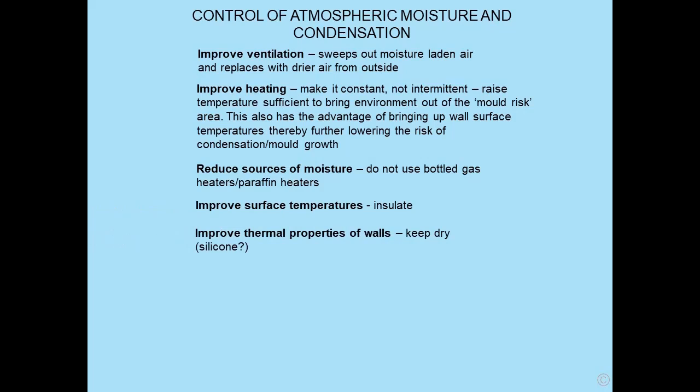Keep dry. For example, if you take a solid wall and it starts to get full of water from a long rainstorm, one of the factors that affects the thermal property is the capillarity, the air in the capillaries of the wall. If that is replaced by water, then it reduces the thermal property of the wall. So if you've got that typical problem, you could use an external silicone. That will reduce water penetration into the wall, and it has been shown to be effective in allowing the walls to warm up. Dehumidifiers are very popular and effective.